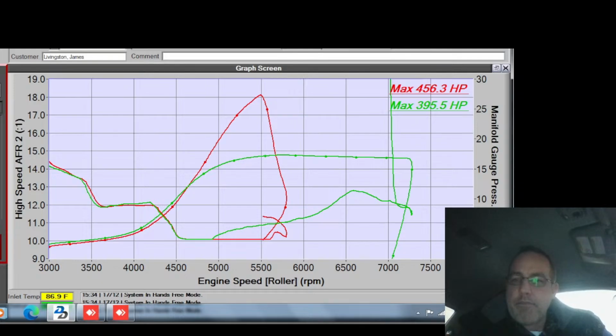Well, let's add to that. Whoopsie, too much. Alright, so I added some fuel in there. It should be richer now. I'm probably too rich up top now, but I'd rather start too rich than too lean like I did already. Okay, and this fuel map only goes to 22 pounds, so that's not going to work. I need more than that.